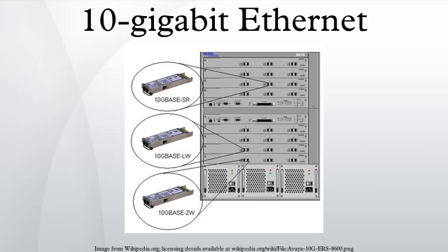XENPAK was the first MSA for 10 GbE and had the largest form factor. X2 and XPAK were later competing standards with smaller form factors. X2 and XPAK have not been as successful in the market as XENPAK. XFP came after X2 and XPAK and it is also smaller. The newest module standard is the Enhanced Small Form Factor Pluggable Transceiver, generally called SFP+. Based on the Small Form Factor Pluggable Transceiver and developed by the ANSI T11 Fibre Channel group, it is smaller still and lower power than XFP. SFP+ has become the most popular socket on 10 GbE systems.